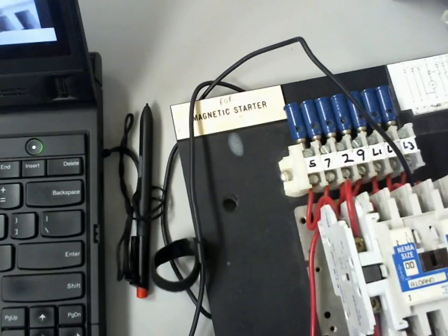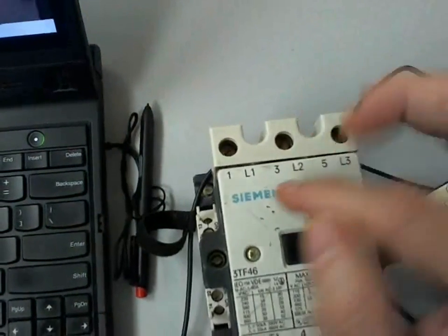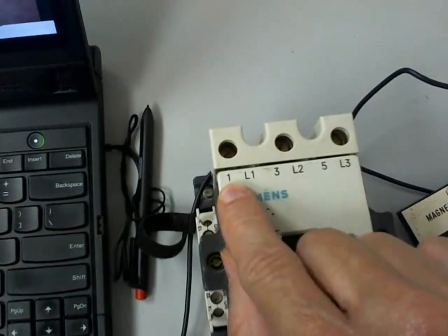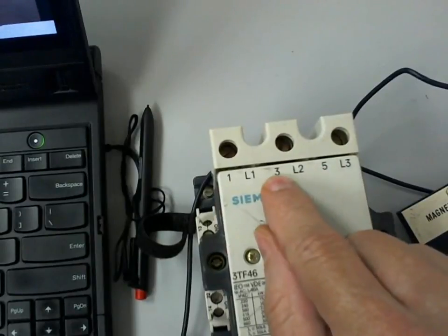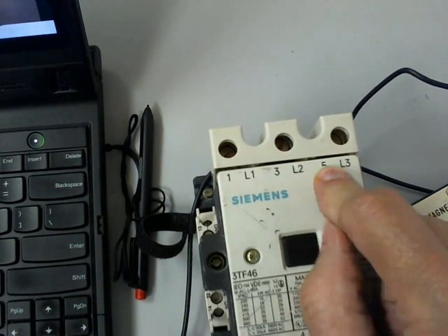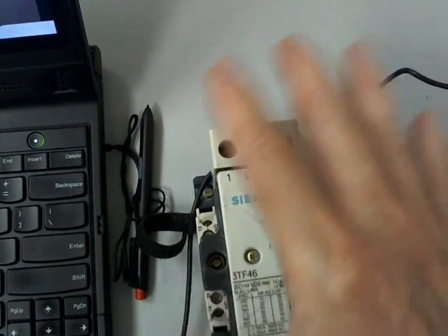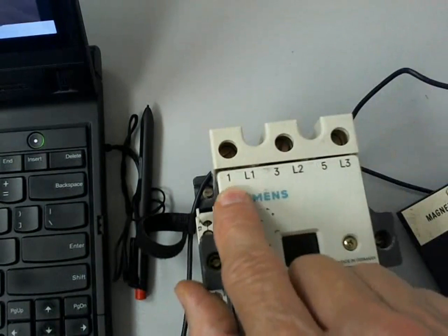No, they got a C on here for coil, and they don't have numbers on the other thing. But here's this relay right here. So this is L1, but they also give it what? Number 1. This is L2. They also call it terminal 3. This is L3, also referred to as terminal 5. So that means I don't have to use this to control L1, L2, L3. I could actually use it as a number, right?